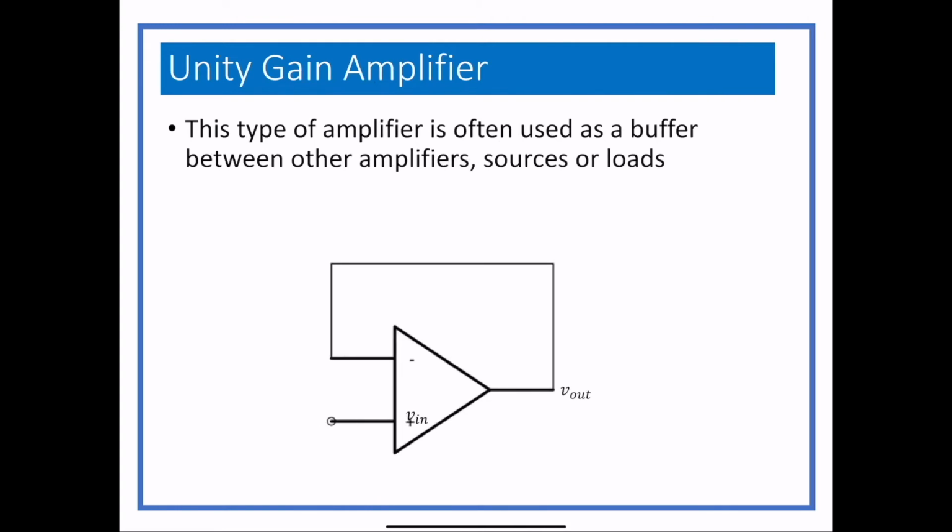And what this means is Vin is just the same as Vout in this particular circuit, because Vin is getting put in, the negative and positive terminals have the exact same voltage, and the negative input is shorted to the output. So that's all it is. Whatever you put in, that's what you get out. I think you build one in lab one day, from what I remember. So it's the easiest circuit in the world, with no resistors, nothing. Just connect a wire from pin 6 to pin 2 and put your input at pin 3 and you're done.